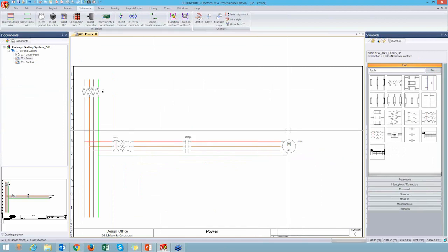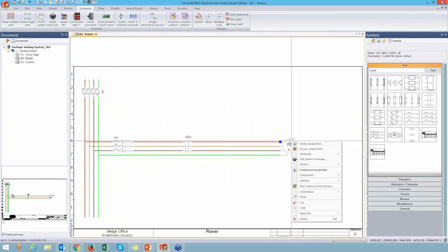Now, one thing that we do in SOLIDWORKS Electrical is once we put symbols in place, we get to actually define what the actual circuitry on those symbols are by assigning manufacturer parts. Now again, we can do this a couple of ways. So just like when you're working in Windows, lots of ways to go about performing a task. In this case, we've got some nice button clicking, button saving commands. So in this case, we would just go to component and assign a part to the symbol.